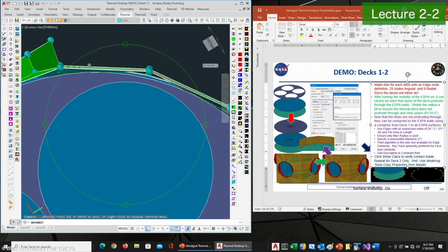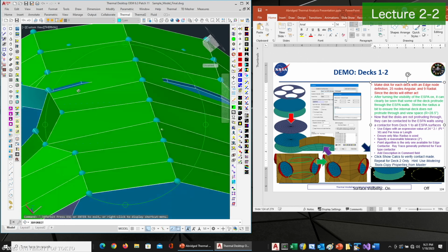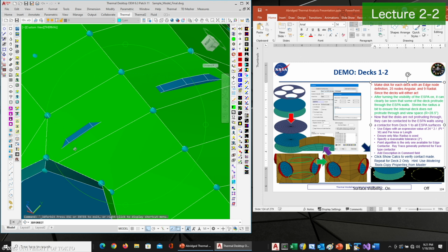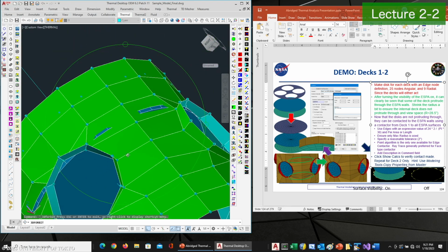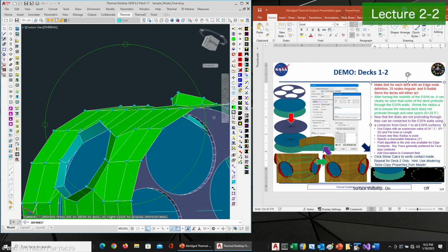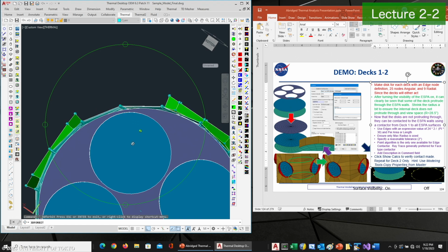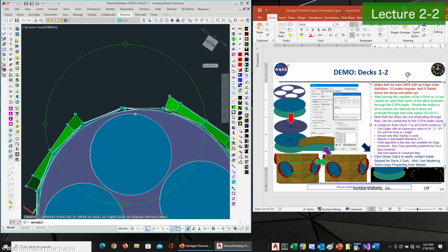I mean, this has a curvature with the arc length to it, but it's really the ones here that we've had to move inboard further or outboard further that cause the problems with things coming out here. And I could remesh this and put another element, do some triangular elements there, if it was really warranted. But what we'd find later is that when we use this 28.5, there is an area where the sun sneaks through, particularly at the beta 90 case, which is basically looking like that down at it.